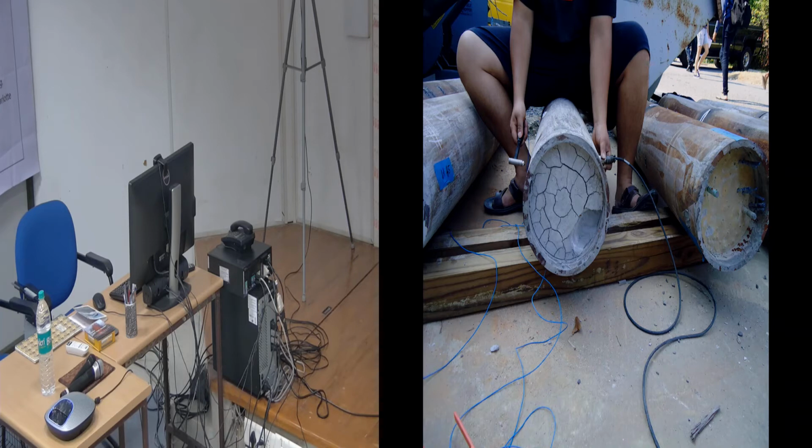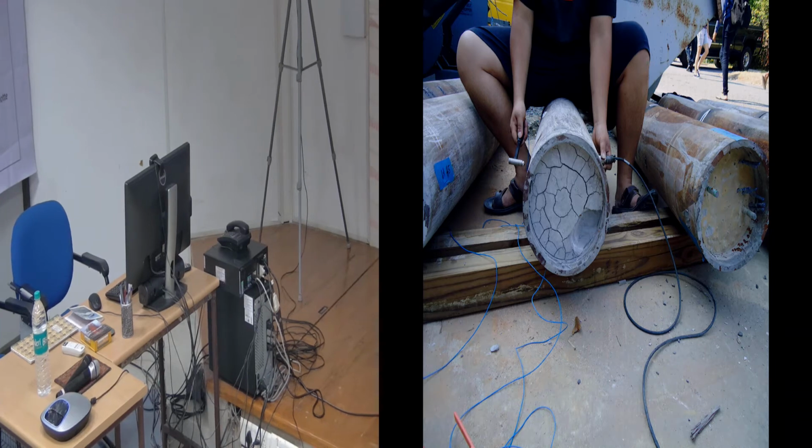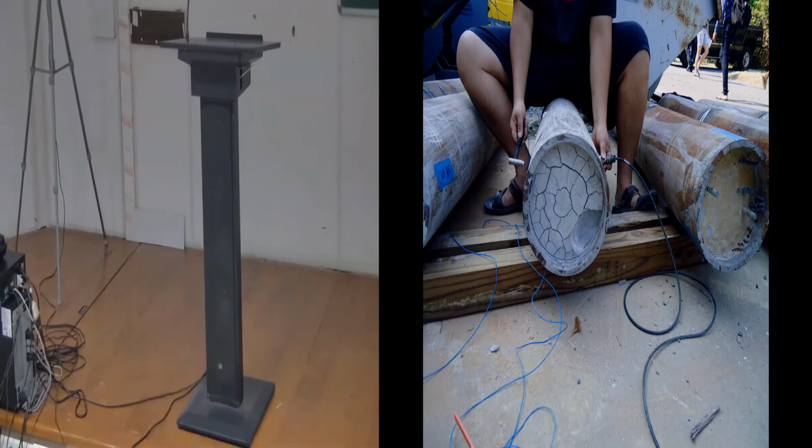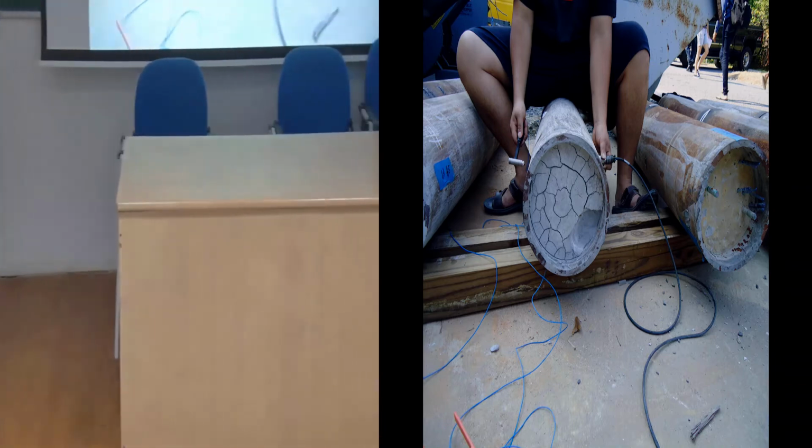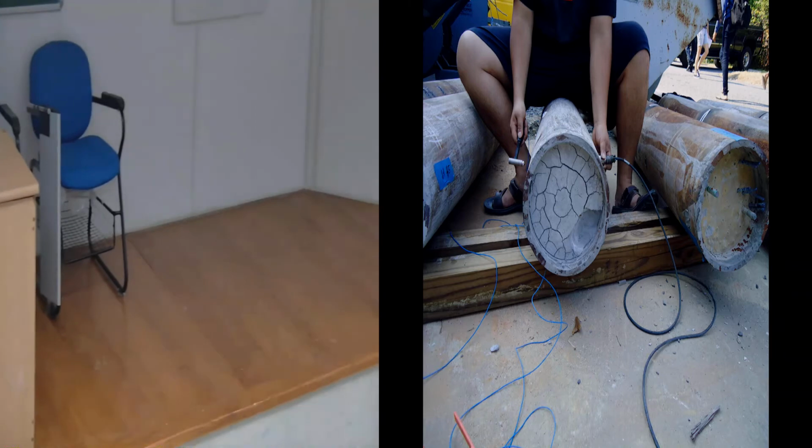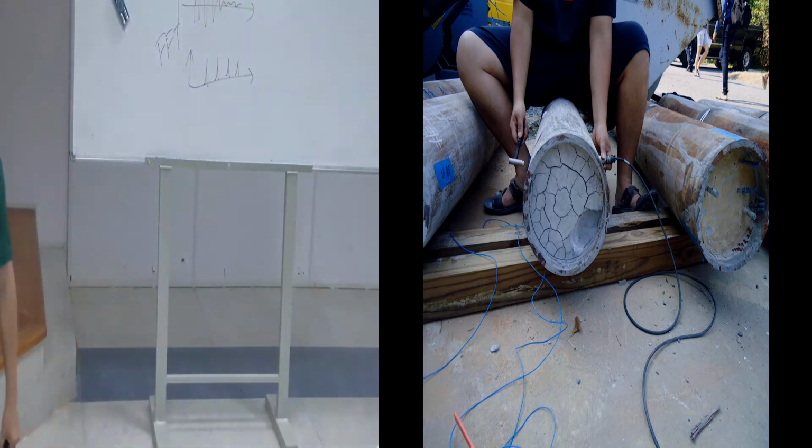Yes, time delay is the way. You can also relate the time delay to wave propagation, but it's a little more complicated. But with one technique you can actually get two results. So that's another advantage of doing an impact-based vibration testing.